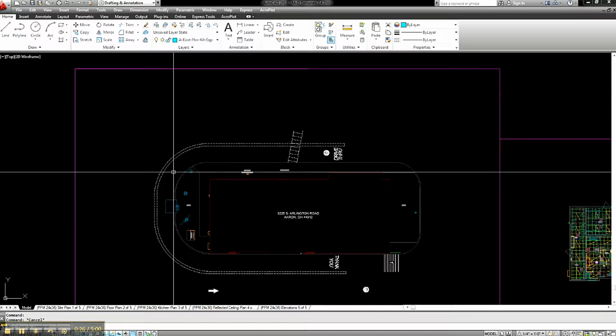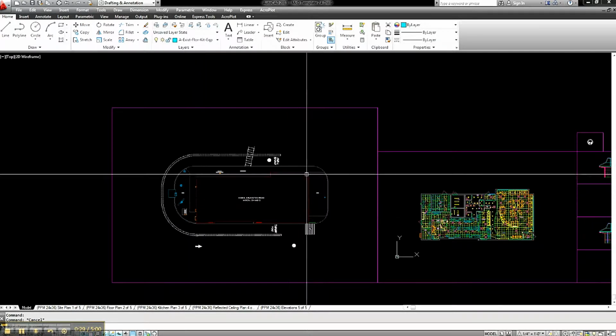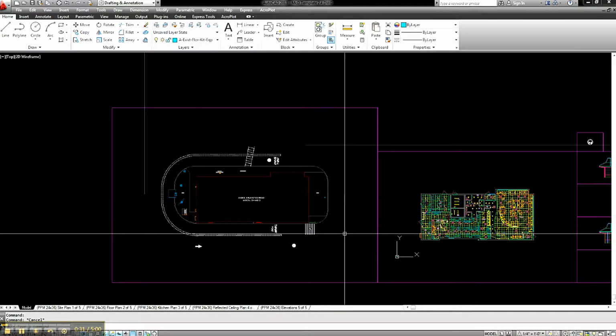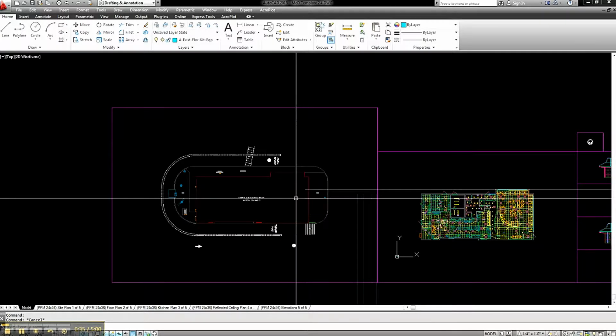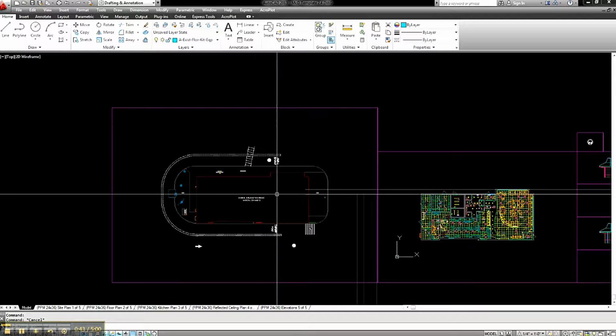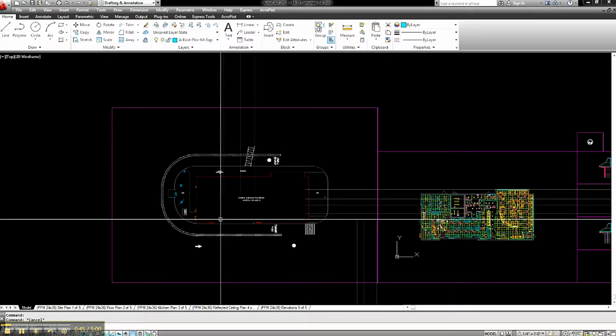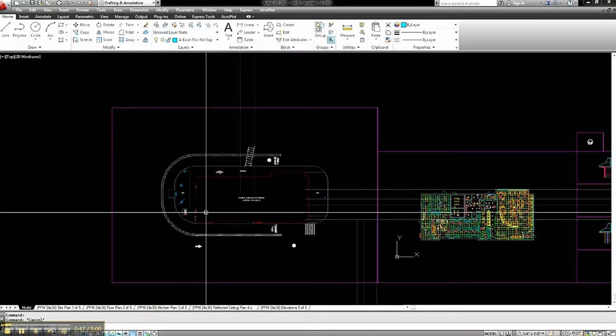So we can start with the site plan. We want to center the line work of the site plan to the box, which I have already done. And with that said, once you go into the layout tab, you can just zoom the object, adjust your scale, and your plan will be centered. There are easier ways to do this. I just use this for consistency.